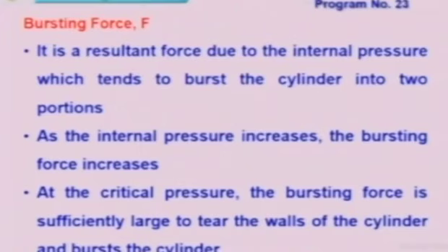Now let us try to understand how exactly this bursting force acts. So again, I am just trying to show you an animated view of a cylinder. So right now I have a cylinder which is subject to some internal pressure. Now understand that the pressure keeps on increasing. So we can expect that as the pressure keeps on increasing, the three stresses that we are trying to talk about, the circumferential stress, the longitudinal stress, and the radial stress, keep on increasing.